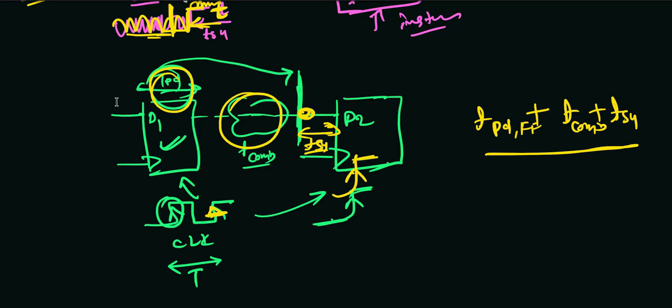So this flip-flop setup time constraint says, I can sample this data, but at least I need the stabilized data T setup time before. This is the setup time constraint. So this much time we are taking and T setup time is the margin. Now you can sample the data. So this is the minimum time period. Now this clock edge can come after this time period also.